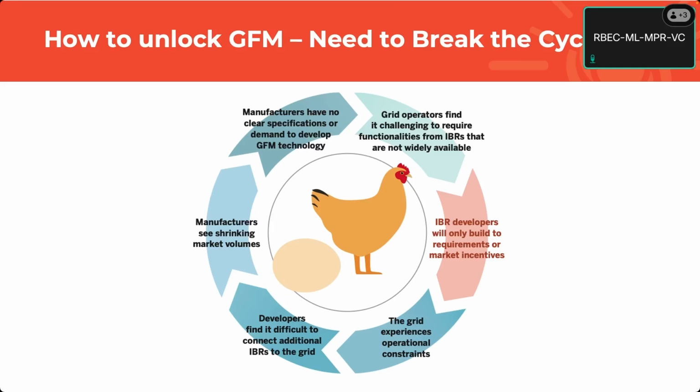We got the models and did a detailed study. We showed the oscillation. We did some short circuit work to show that this is actually a weak system. You didn't think it was, but it is, and that's why you're unstable. You're hitting small signal control limits. We showed that if you turn grid forming on, it's solved. Everything's flat. But the utility is not allowed to use grid forming because it's, quote unquote, untested.